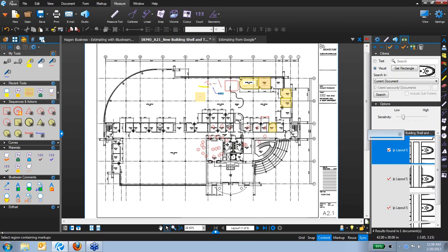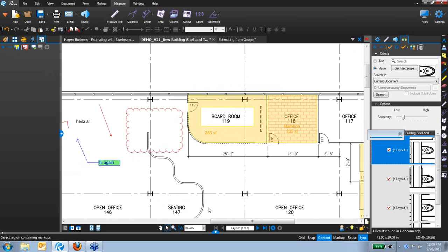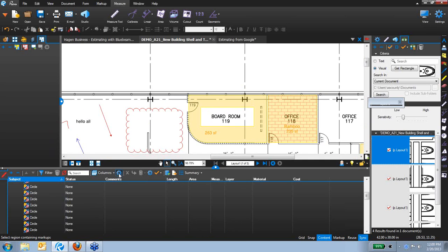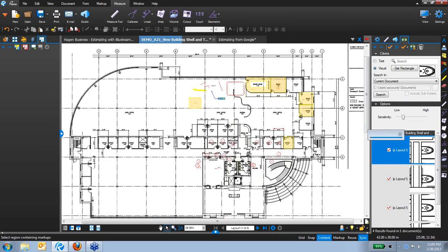It really does save quite a bit of time when you're trying to figure out what room something is in and that you're going to share that with other people. All right, let's jump right into spaces real fast. This tool is near and dear to my heart because I got to help create spaces. Being someone that worked in the field, that did punch lists, that did some quantity takeoffs, there had to be a better way to track where specific issues were. So instead of having to go down here and create a custom column that said a particular markup was in area A on the first floor in room 101, we figured we'd automate that a little bit by actually creating spaces.